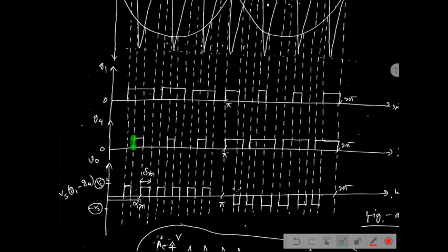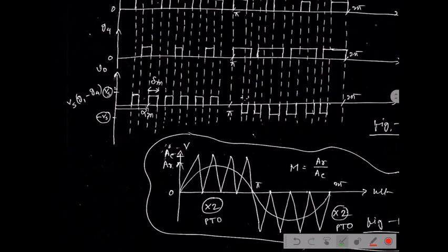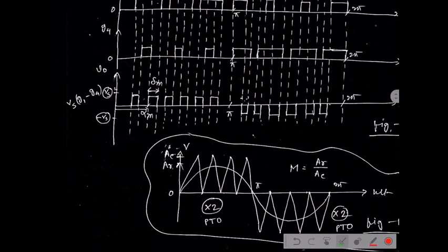If there is any delay which is introduced due to some uneven condition, then if G1 starts working while, at this particular instant, G4 is in on state, that means immediately G1 and G4 will be short circuited. Okay, so to avoid it, we can use this kind of signal also. As well as we can reduce the number of signals.